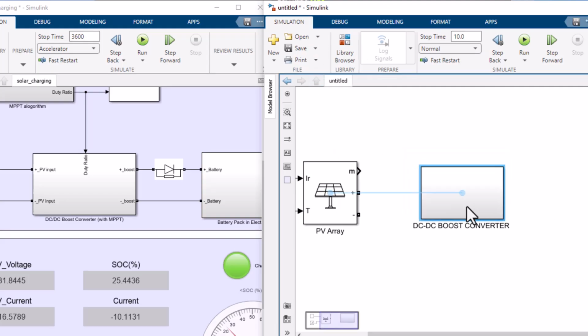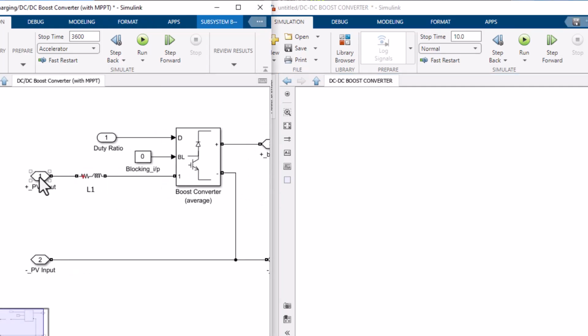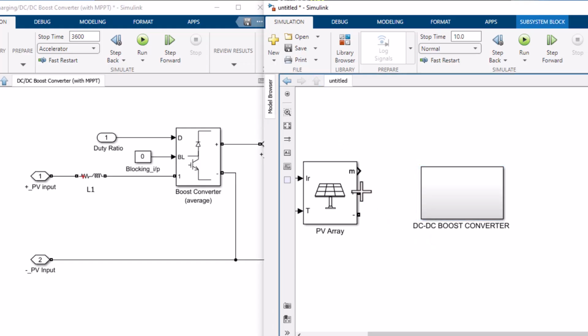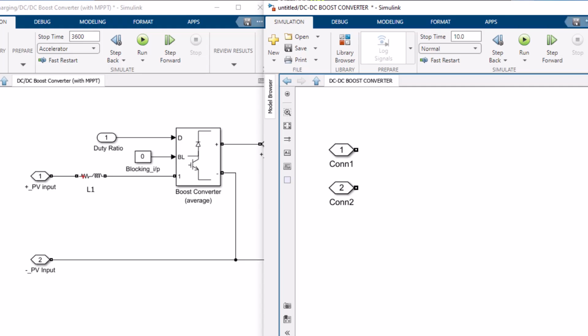You can see. So how to connect the connections and put them inside? Just go inside, and if you see here, I took one positive and negative. If you make a connection port here, actually this has to go inside, but it is created automatically if you press plus and minus and it goes inside. You can see the software automatically created the connection port.